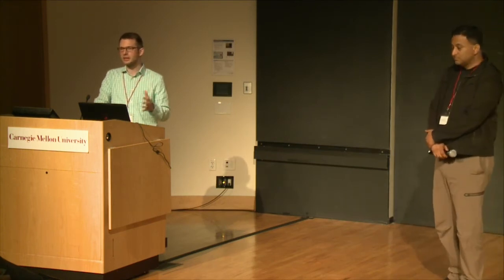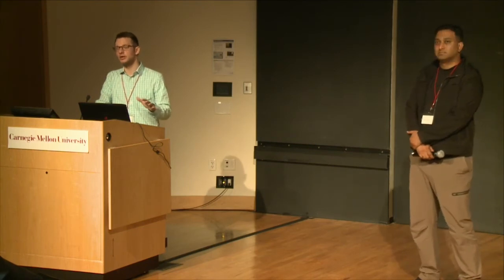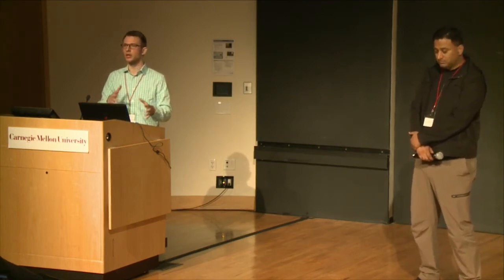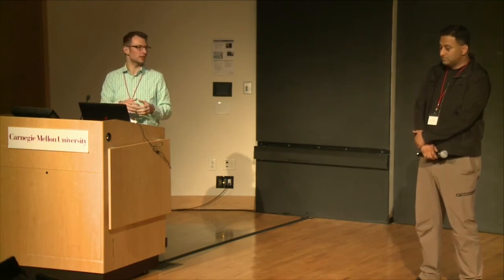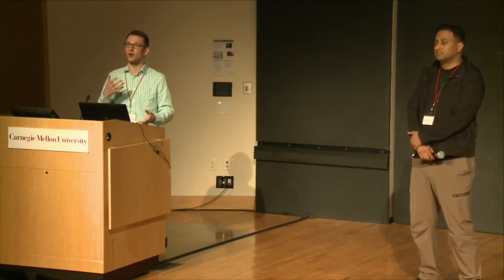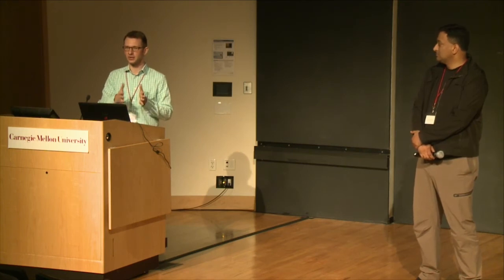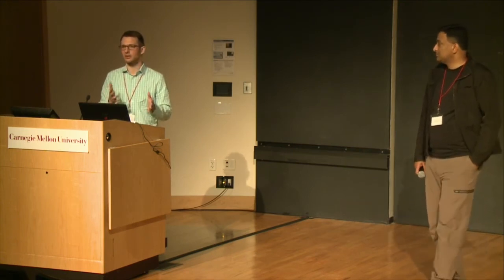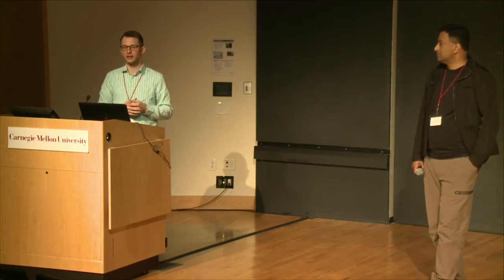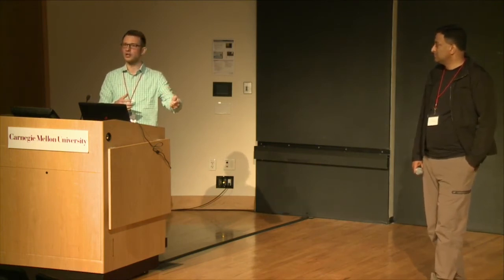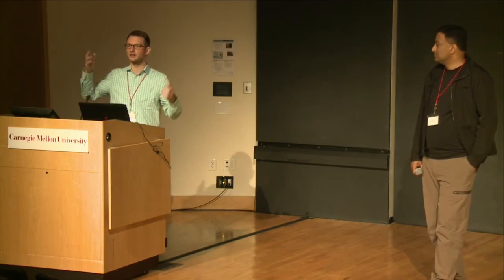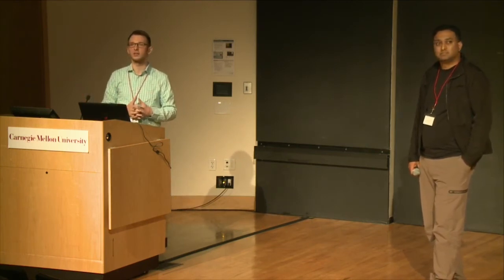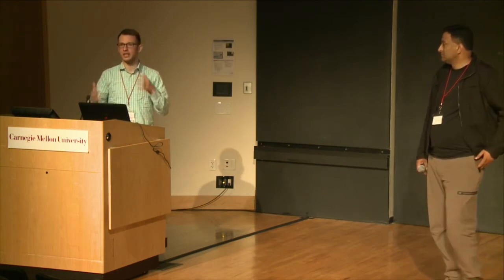So you can operate these SPADs also in different modes. Some SPADs support pre-binning on chip into histograms, which allows you to read out many more timestamps, although in this case you usually sacrifice the timing precision. But if you're interested in a larger dynamic range, reading out more data, where maybe you only have a few photons detected in one area, but thousands of photons detected in another area in your image, some systems support these types of pre-binning operations.